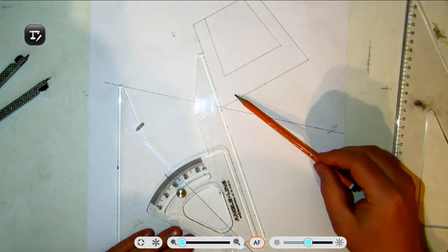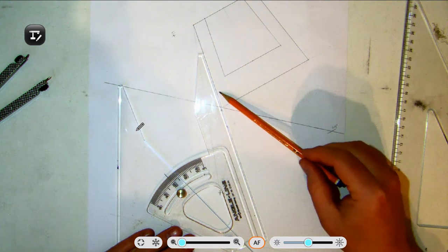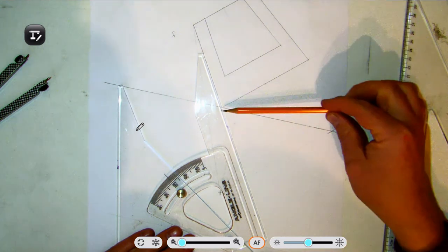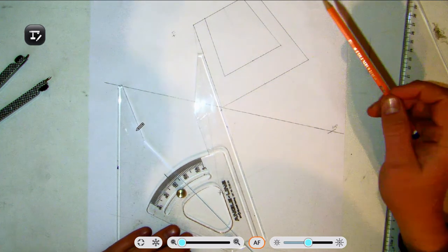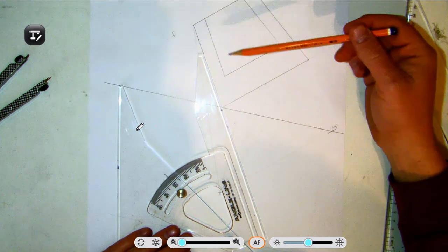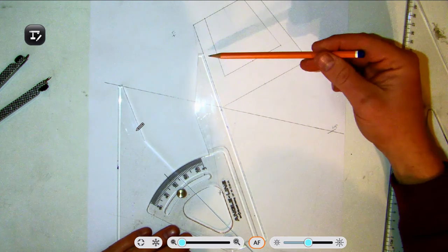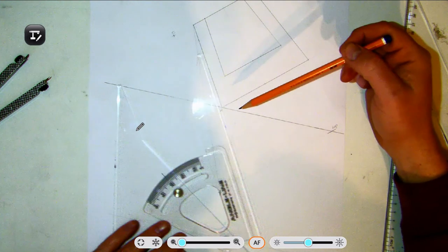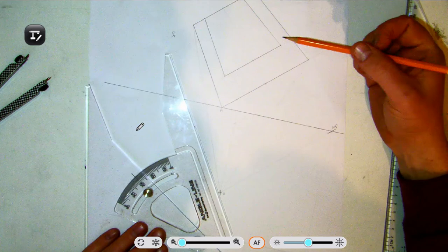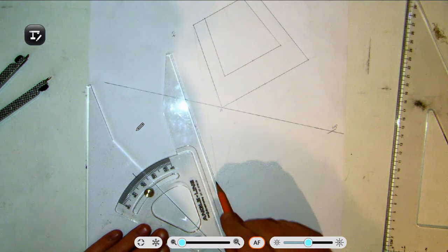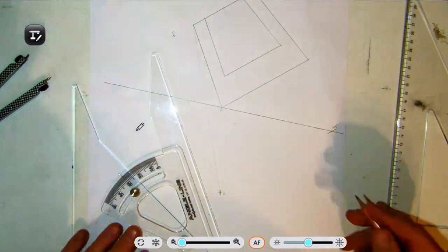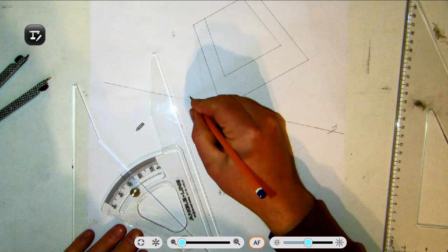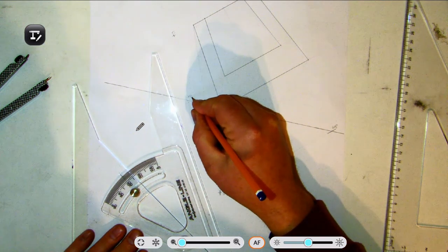We are told this is 80 degrees inside here. So 80 and 30 is 110. That means the remainder of this has to be 70 degrees. So these lines are drawn at 70 degrees. This edge is at 70 degrees, this edge is at 70 degrees. So from the spectator, bring up a line parallel and mark off the position for the vanishing point. We will call this VP2.